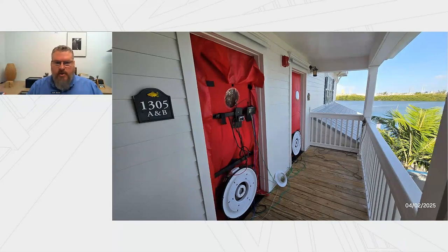In terms of guarded testing, in multifamily, this is done a lot. This is actually a resort in the South Florida area. They were having humidity control problems. They wanted to know, is it the enclosure or is it leakage between units? So in order to do that, we had to do guarded testing so that we could get all of those differing values.